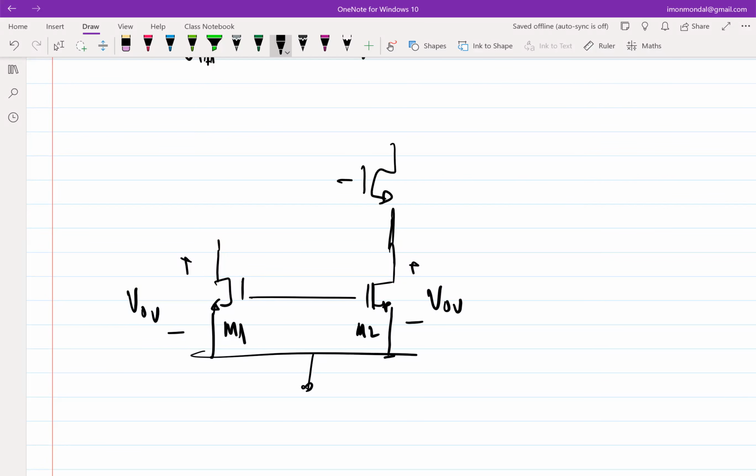We will require this Cascode transistor. That we definitely require. So if I require a Cascode transistor on the left branch, I'll also have a Cascode transistor on the other branch, right? Because mirroring ensures that whatever you have on one branch, it should be there in the other branch. So this should be there. But what is absent is, I don't know how I am setting the gate of M1, correct?